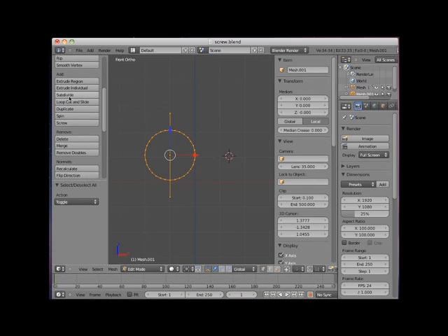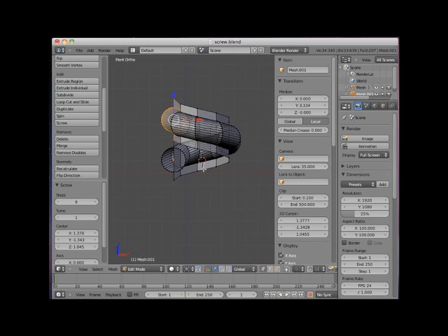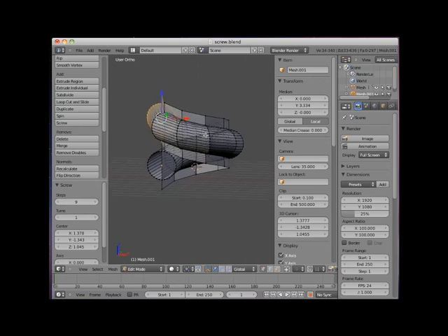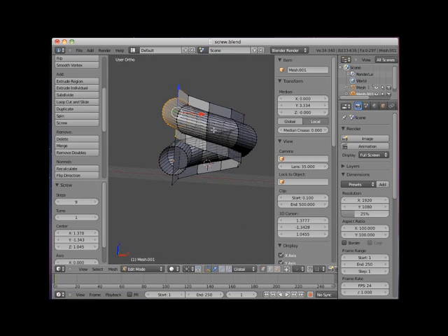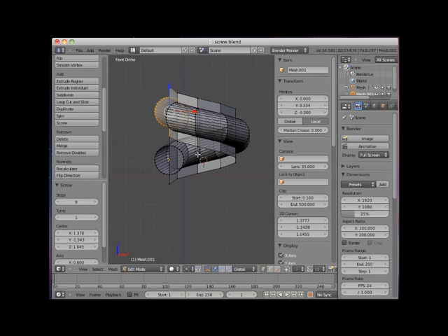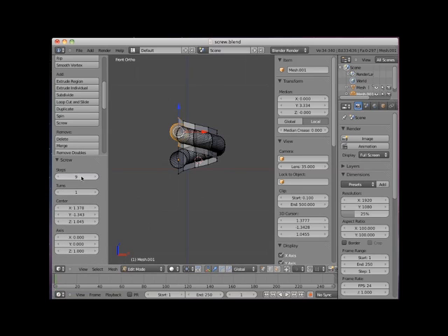I'll now press the Screw button located in the 3D Editor Viewport tool panel. Notice that the screw operation spun the selection set around the z-axis one full revolution, and it translated it upwards the length of the polyline. The controls for the Screw tool are displayed in the 3D Editor tool panel once the screw operation has been executed. By default, the operation consists of one turn and produces 9 segments.